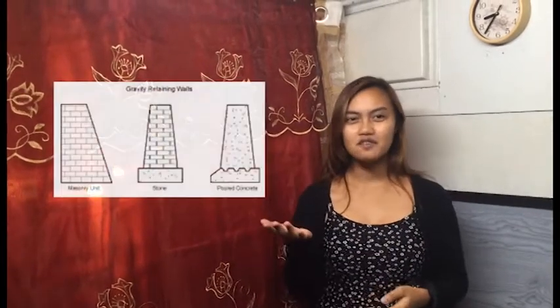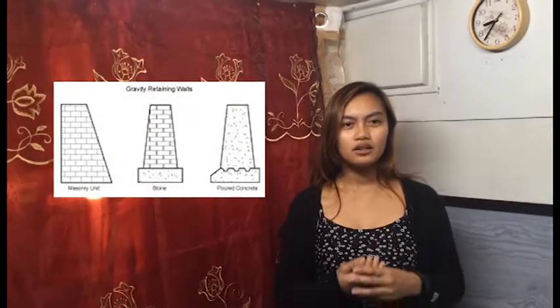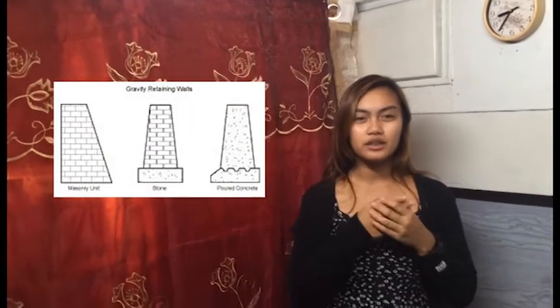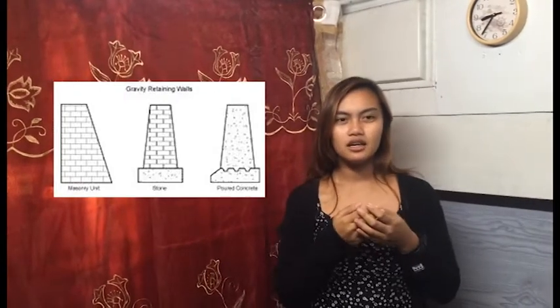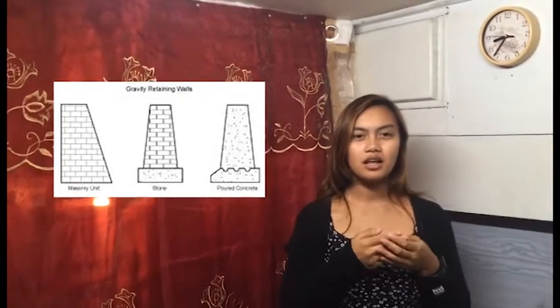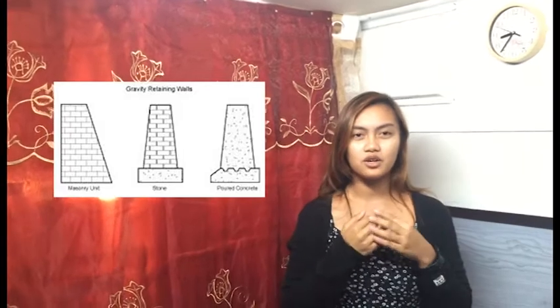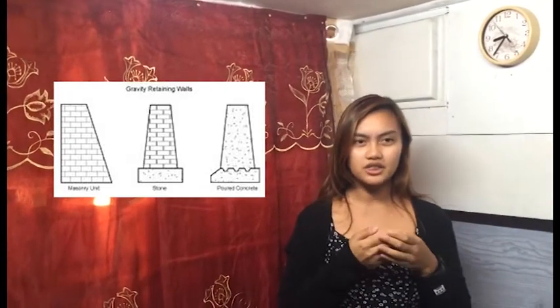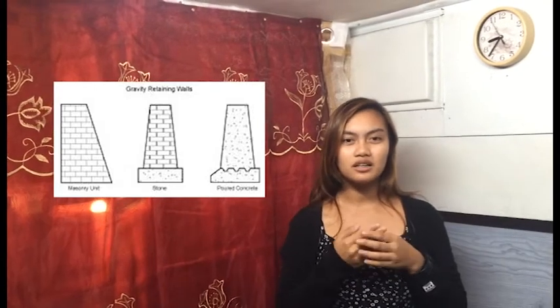There are four major types of retaining walls. First, the gravity poured concrete retaining walls. Gravity retaining walls depend on their own weight and any soil resting on the concrete in resisting lateral earth forces. They are generally economical up to 10 feet in height for cast concrete structures, and usually are sufficiently massive to be unreinforced. Monolithic cast walls are generally formed on site.